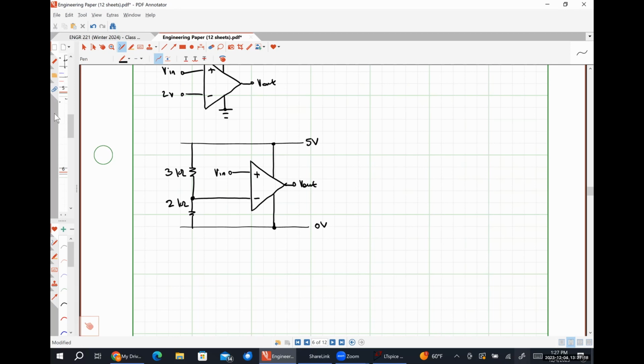I don't want it as a function of time, I want it as a function of VN. So I right click down here and I change my quantity plotted from time to the voltage at node VN. Now this is V out on the Y axis, VN on the X axis. It's exactly how we drew it in class too. So this is right? Yeah, perfect. Okay, thank you. That's all I had.